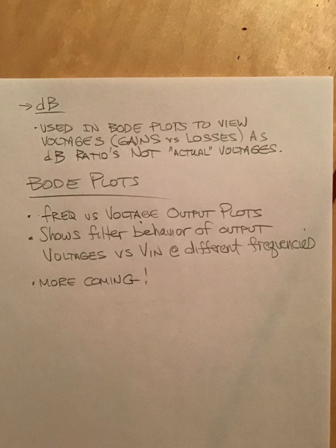What else do we want to talk about? Let's talk about the dB, because it's used in what's called a Bode plot to view voltages versus gains. When we make this plot, which I'm about to draw, for a low-pass filter and it cuts off at a certain spot, the dB will be in this region here, replacing voltage, and your frequencies will be down here. This is called a Bode plot.